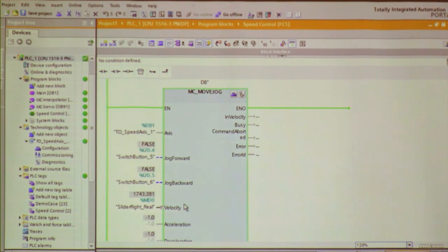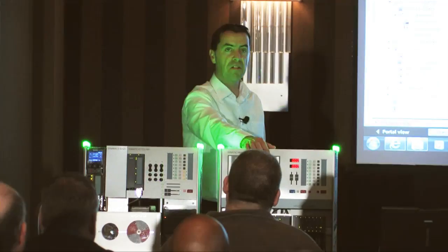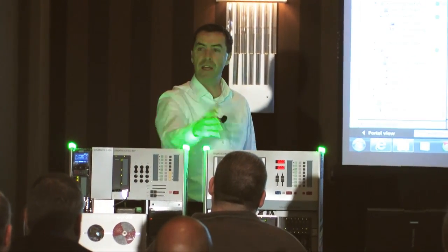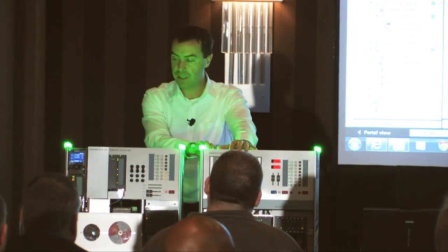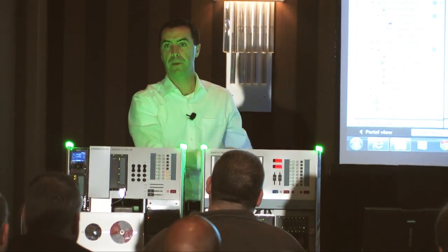I could now add in the HMI wizard that Keith showed yesterday, drag this wizard in, pull in a screen. Normally that's what I have. All the screens that I had on here, I have them in the library. I could pull them in and I can connect HMI, PLC, and drives very quickly.